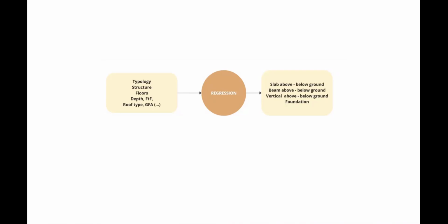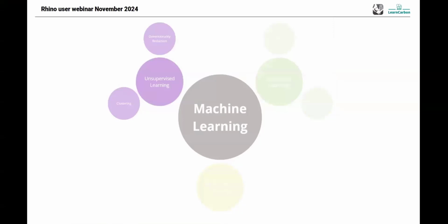And also, of course, now we are in a Rhino context, but we could reuse this Python code for other software as well. I'm not going to explain this too much, but we did that using a self-organizing map, a kind of old school machine learning. There is a Kohonen network plugin in Grasshopper that we used to create the synthetic dataset. So we created a script that could create a lot of buildings with a lot of entries, which we then ran overnight with the slow plugin that I mentioned, and then had the final dataset that we could train the model on.